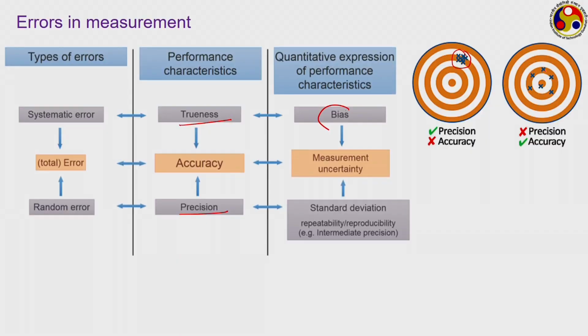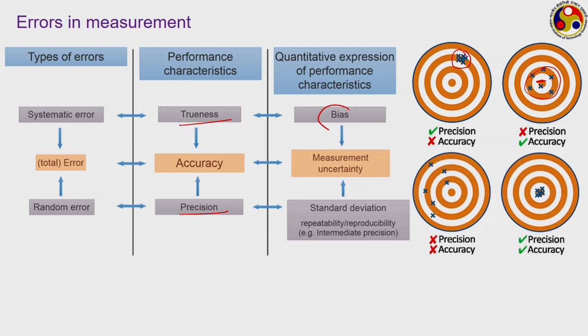Similarly, when the system is not having any kind of systematic error, that is a highly true output that we are getting, but random errors are present, then we may find that all the observations are well scattered around some kind of mean, which may be somewhere here in this particular example. Both the errors can be present simultaneously in the system, and that is generally the most practical case.